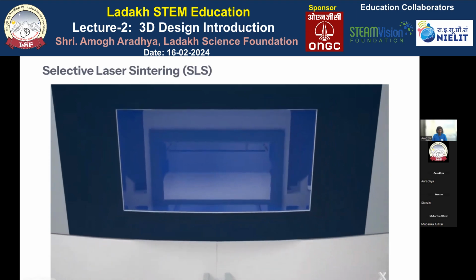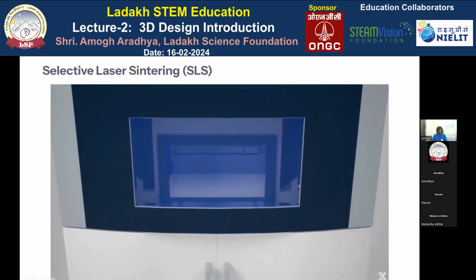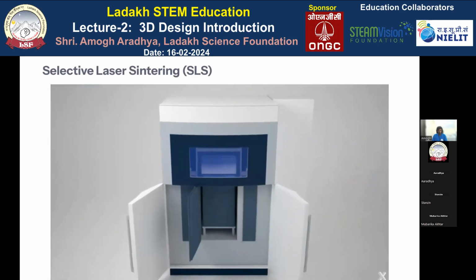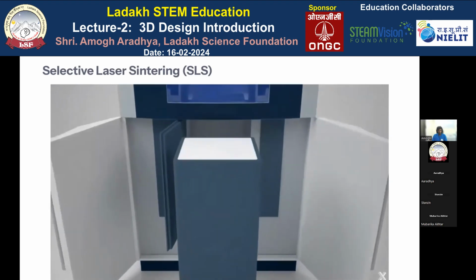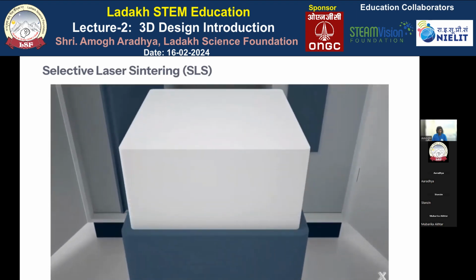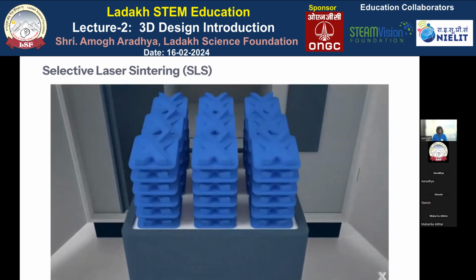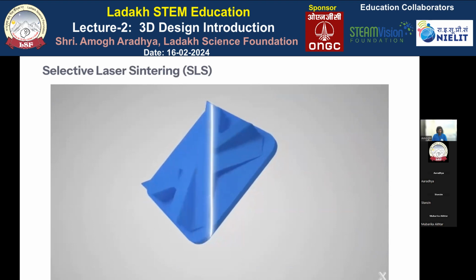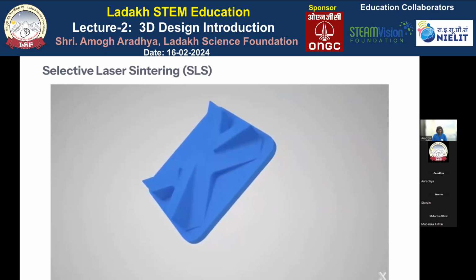Once the printing process is complete, the build chamber needs to cool down to ensure optimal mechanical properties and prevent warping of the parts. The finished parts are removed from the build chamber, separated, and any excess powder is cleaned off them. SLS printed parts come out grainy. If necessary, they can be post-processed using vapor smoothing and media tumbling, for example.